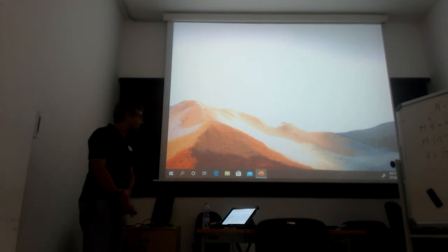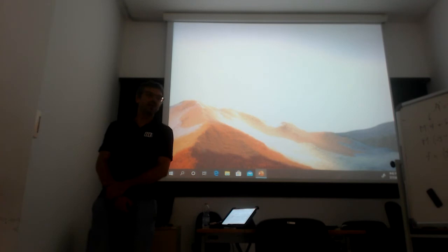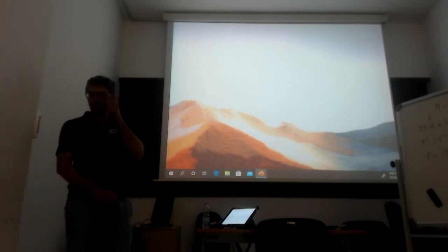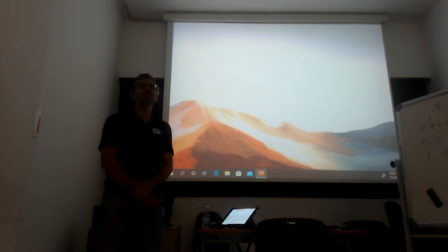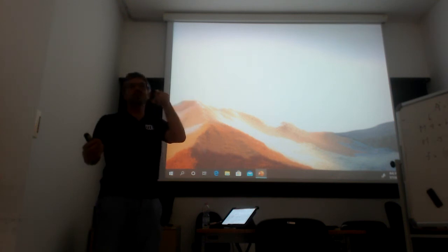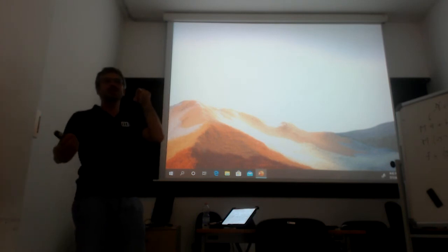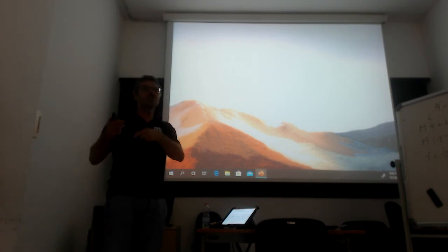Yeah, I would say. But you need to measure the penetration somewhere. Yeah, that's a problem that we faced with the whole body controller on soft terrain. To measure the penetration, you need to use a Vicon system that was estimating the position of the robot in the world, in the inertial frame, and then with the forward kinematics we could see the location of the foot, and then at the touchdown we were starting to measure the penetration,